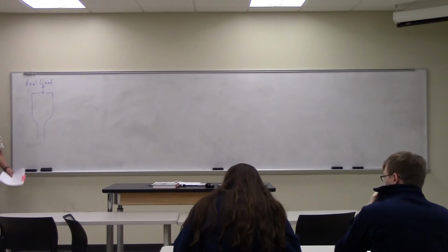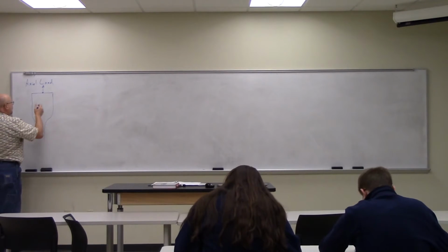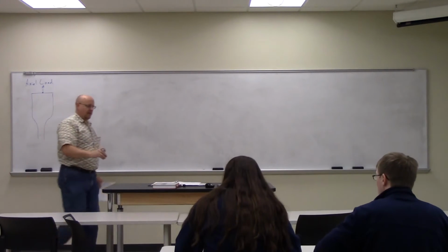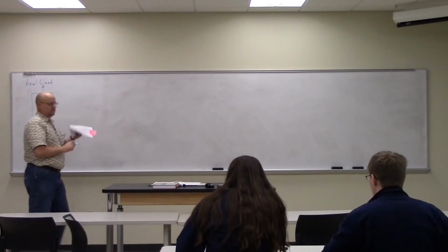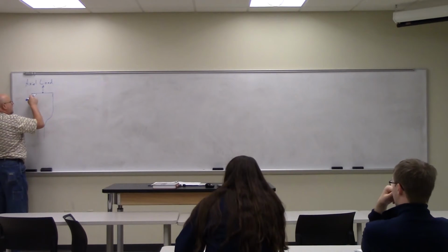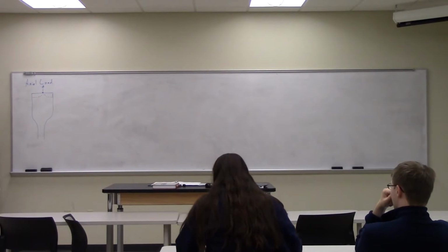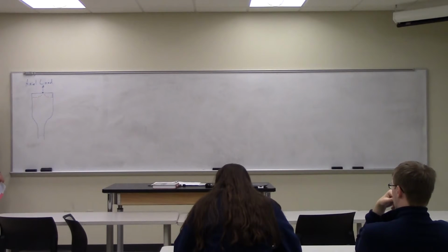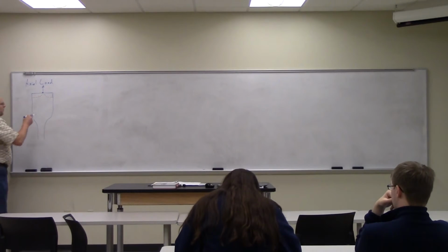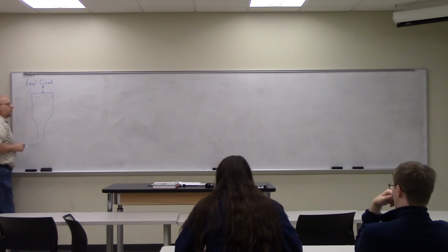Then there's going to be a stress distribution. And if I plotted the stress distribution right here close to that end point, I would find that there is a concentration of stress in the center where I'm pulling it, which kind of makes sense. If this were a piece of rubber and I were pulling on an eye hook, it would bulge up at that point where I was pulling it. But as I get further and further away from that point of application, that stress will tend to become more uniform.